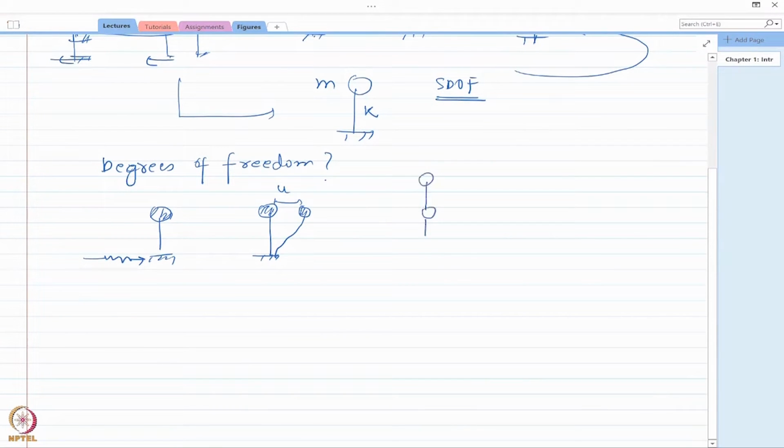So this is degrees of freedom. Similarly, if I have a multiple degree of freedom system, how many degrees of freedom could there be here? One would be for this, one for this, and one for this. So I could have a single degree of freedom system, or in this case a 3 degree of freedom system, which is a multi-degree of freedom system. You have to keep in mind how we represent degrees of freedom. Now I'm going to show you some examples in which you have to find out how many independent degrees of freedom you would require to represent the displaced position of masses in the body with respect to its original position.